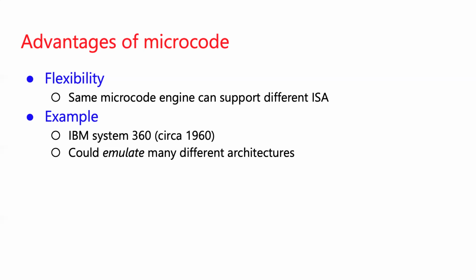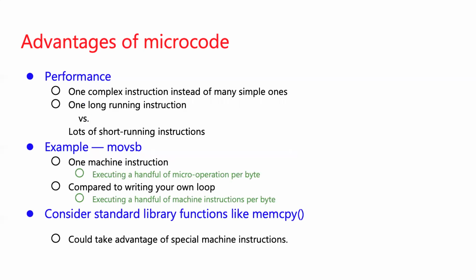They had a processor, at least the logic of a processor, that could run a particular instruction set, but with different or additional microcode, you could change the instruction set it was able to run, just by changing the assembly language instructions that it recognized and writing microcode to implement those various instructions.